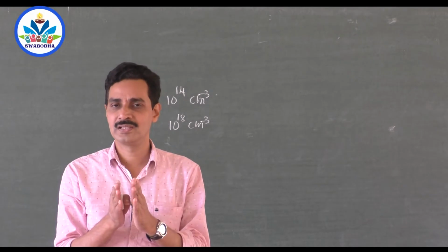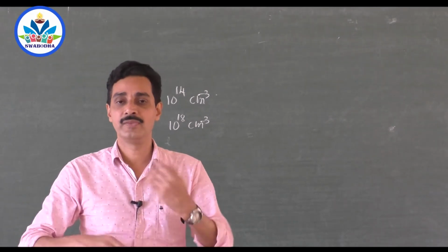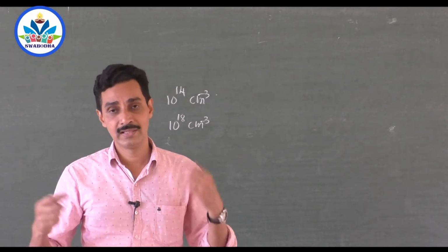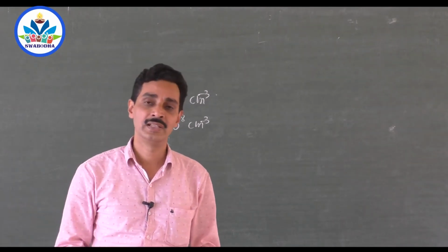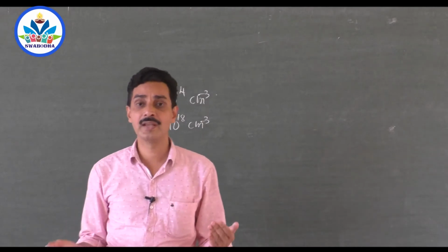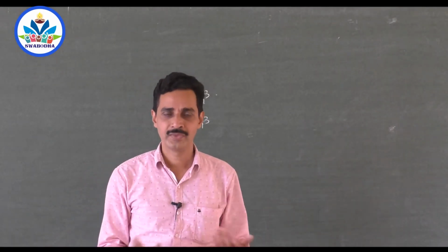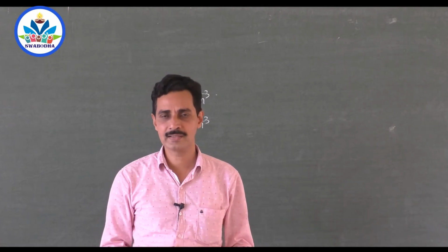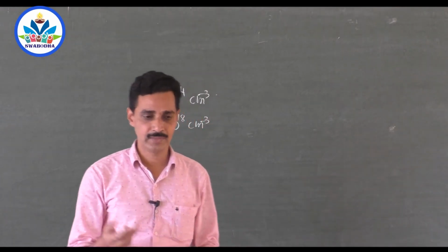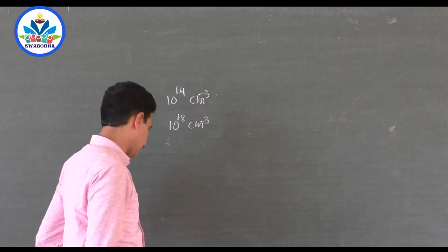of the depletion region is small, and that develops a very strong electric field, and when it is reverse biased, that electric field can knock out electrons from the silicon atoms. So they create more current in the reverse bias, that is Zener breakdown, and that current increases but the voltage remains the same, that is the breakdown voltage, the Zener breakdown voltage.